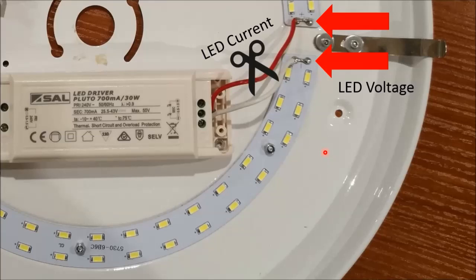Then there are 1 to 10 volt dimmable drivers and 0 to 10 volt dimmable drivers. Officially 0 to 10 volt must go to standby if the voltage goes below 1 volt. Anyway, both work for our system as you have a relay main switch in your interface.